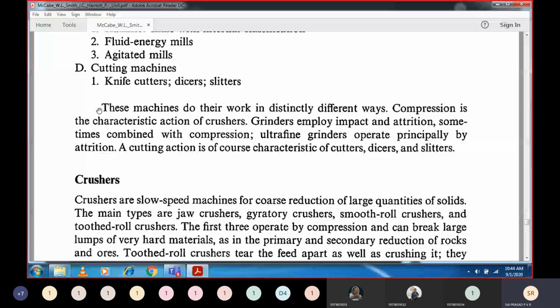And in the fluidized energy mill, we use high pressure steam, which is injected through various nozzles to create turbulence, and then we introduce small particles, and they go in a loop. By pushing each other or pushing against the walls of the container, the size reduction takes place. So as I said, as we try to go down, the efficiencies are decreasing.